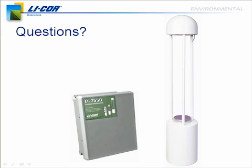Okay, Tatiana, that's a great question. I'm glad you asked about that. Because it is a new instrument, we've only been collecting data with the LI-7700s for a few years now, but we do have some long-term stability data that we can use, and we've certainly had instruments deployed for longer than 6 months at a time, brought them back in and performed factory calibrations and drift checks, and seen no calibration changes at all. So over periods of at least 6 months in field conditions, we've seen absolutely no change in the calibration, and I would expect that number to continue to increase as we get more data from the field that we can analyze.